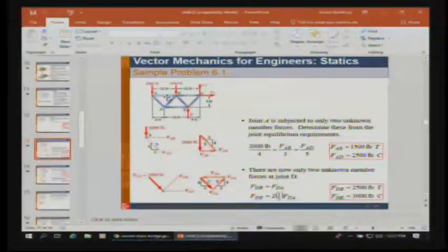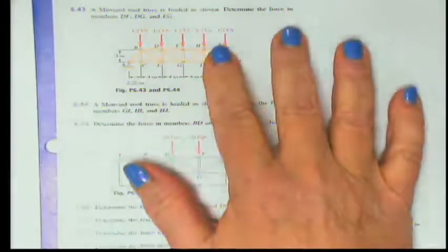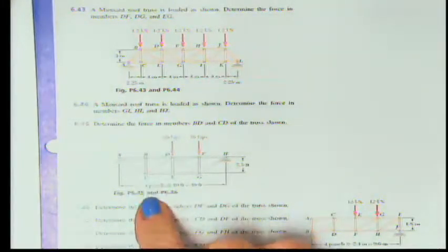It looks like it switches if you think about it from analyzing it, because the sum has to actually be zero, whether it's bearing tension or compression. So if it's like a positive 1,000 on one side, it's going to be a negative 1,000 on the other side. But we define it by being tension or compression. And doing that, we can work through an entire truss and determine what the forces are in each of those structural members. All right, now to illuminate that, I'm going to work a problem from your textbook so that you'll have this in your notes.